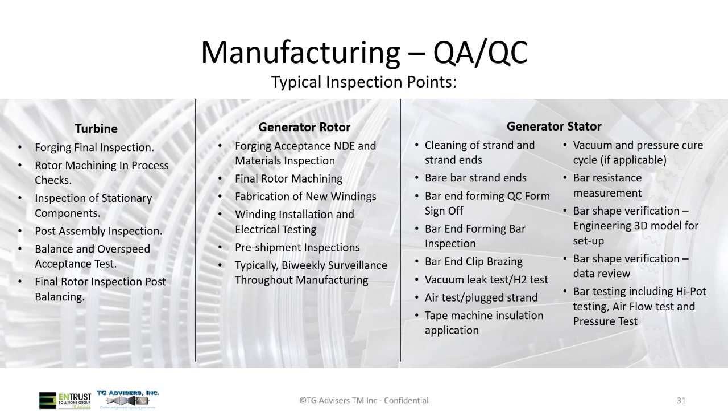And once you get through the design review process, now you're into manufacturing. So we're looking at QA, QC checks along the way. You'll typically get informed of non-conformances as they occur if they impact form, fit, or function of the unit. But also, one of the things you may want to consider in your contract is having notification of all NCRs, or when you go on these witness checks, typically you have inspection reports depending on the process you're doing.